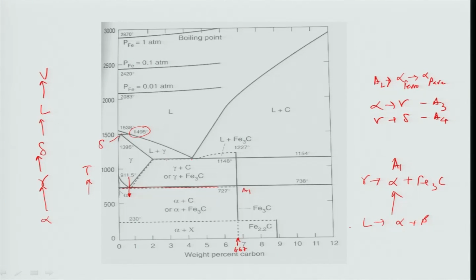In the next class I will explain in detail how the eutectoid transformation happens. But before that, in the time left in this class, I would like to tell you 3 important aspects. As you know, in the eutectoid reaction, which I have written as alpha plus Fe3C, 2 solid phases form directly from one solid phase. One is a very soft alpha iron, the other is a very hard compound Fe3C. So this is nothing but an in situ composite between a soft phase and a hard phase.